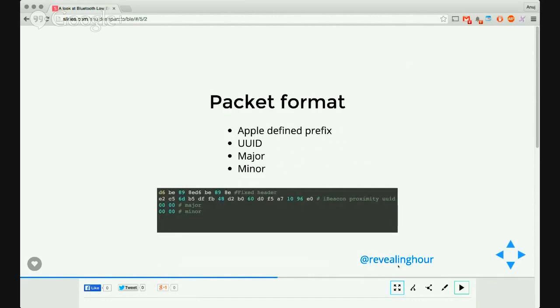There is no kind of two-way communication in the iBeacon format. The best analogy to explain a beacon is a lighthouse. A lighthouse is consistently emitting light from a lamp in all directions, but it does not take feedback from the ships that it guides. So the lighthouse is basically the beacon, and at fixed intervals it will broadcast a packet. That packet is unique in some ways. That format is the one which has been licensed by Apple, so only iBeacon compatible devices are supposed to use that format. For example, the fixed header will identify that the packet that follows is going to be an iBeacon packet.